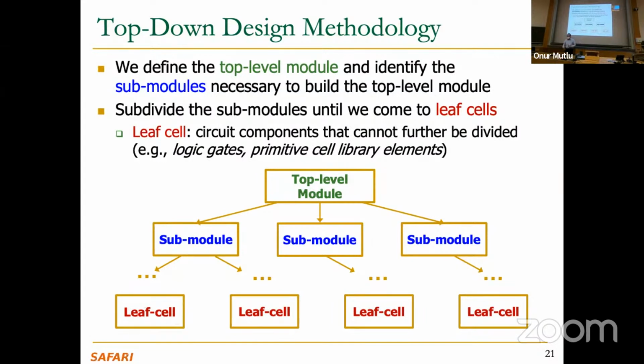So basically, your hardware description eventually ends at these leaf cells. But remember that leaf cells can be at different levels of abstraction also, if the library provides that abstraction. In fact, it's very nice to have that abstraction. Somebody designed this beautiful multiplexer, 8-to-1 multiplexer. I don't care how it's implemented. That's my leaf cell. If I'm going to use that in a submodule, I'm going to just instantiate that leaf cell. I'm not going to go into the AND or NOT gates that implement that leaf cell. Okay, that again tames complexity.